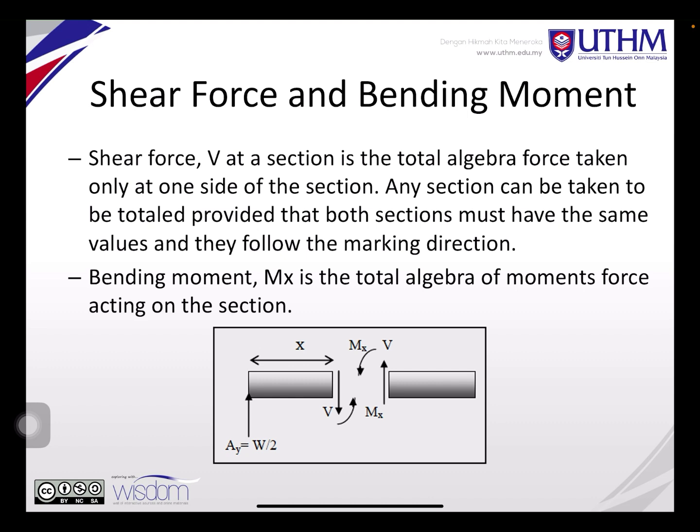Shear force, the V: you can see the V here at a section is the total algebraic force taken only at one side of the section. Any section can be taken, provided that both sections have the same values and they follow the marking directions. When you have a beam, you can cut at any section, and when you cut, you will have a picture like this.